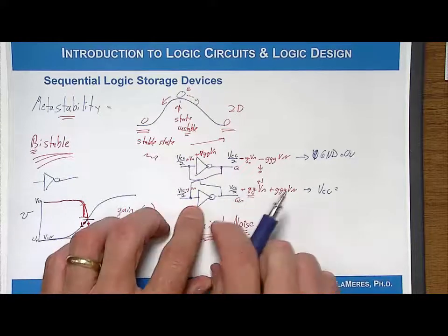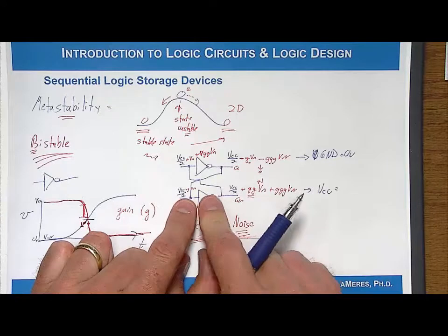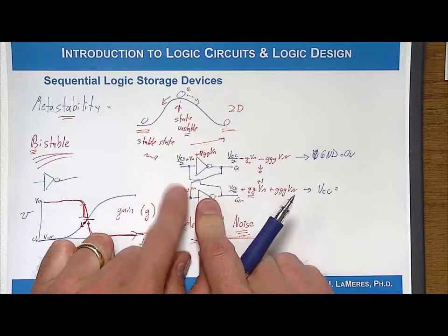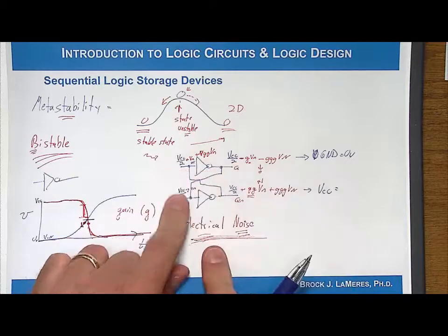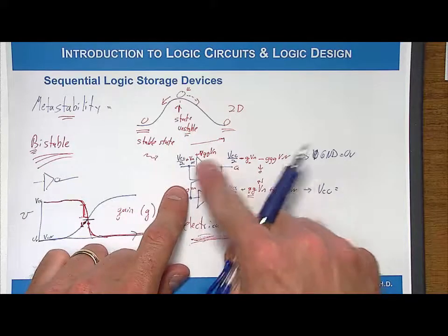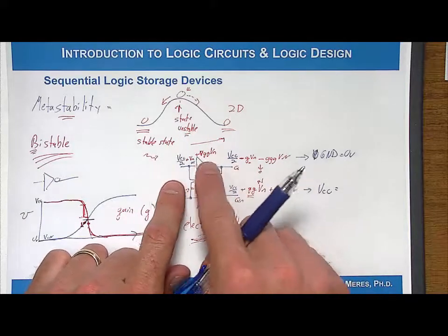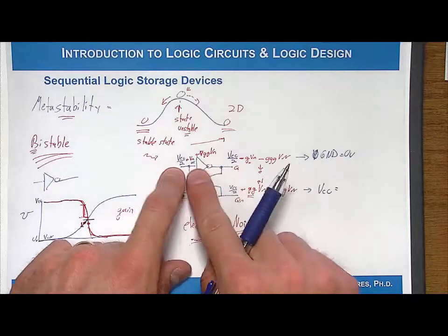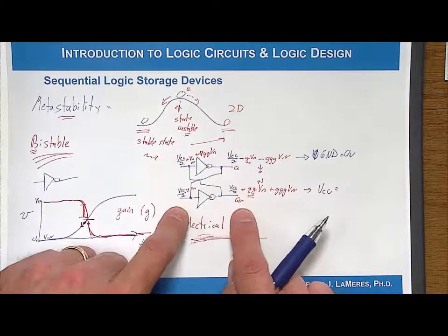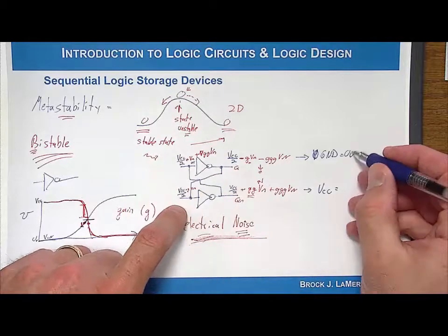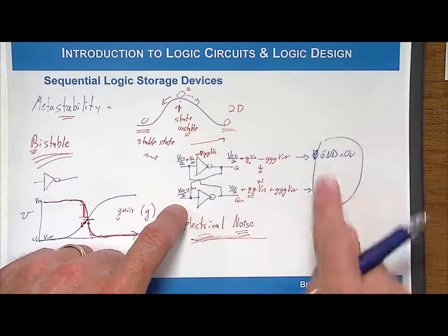So this is an example of a device that was in a metastable, unstable state, and it was disturbed very minimally with electrical noise, and that caused us to go into a runaway situation. You can say that the device went metastable as it transitions to one of these other, more stable states, but it did ultimately land in a stable state.